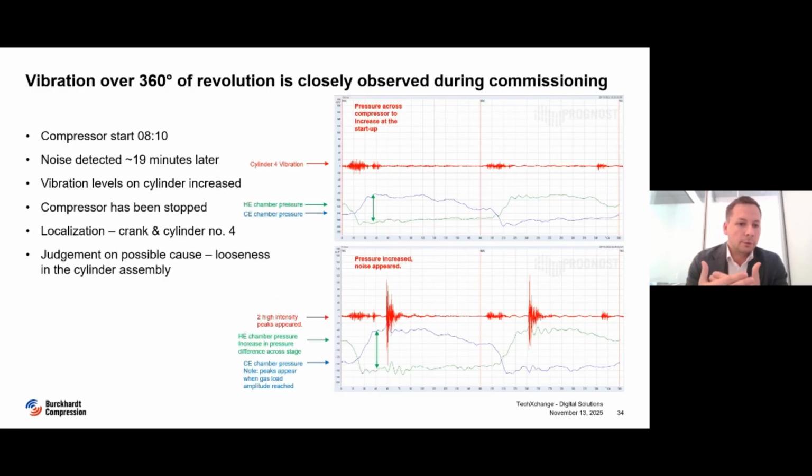An activity of such scale, when the compressor had to be rebuilt, of course, is very complex. Many things have been done. And one morning, the compressor was started. First, it starts without a load, then pressure difference across the compressor slowly increases. And approximately 20 minutes later, we saw in the system high vibration peaks.